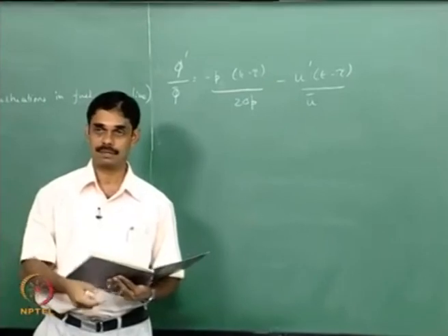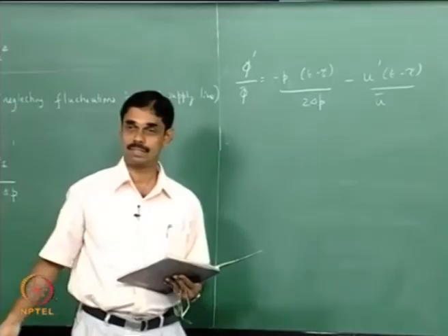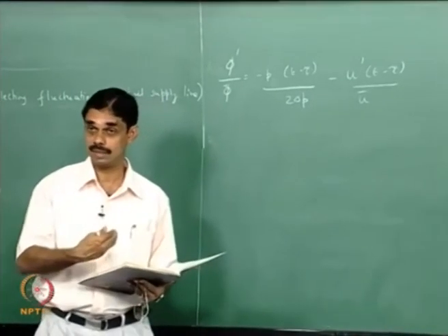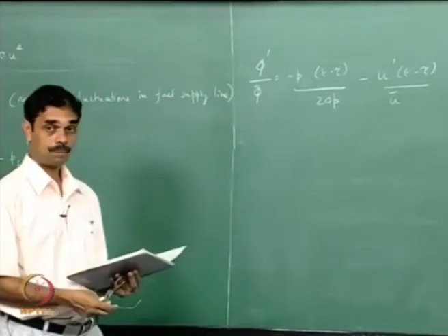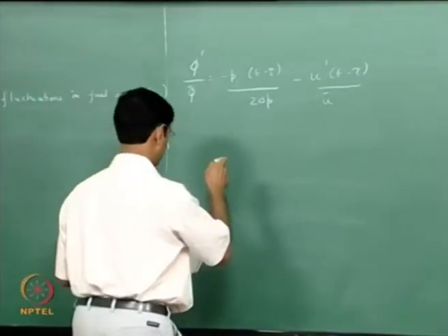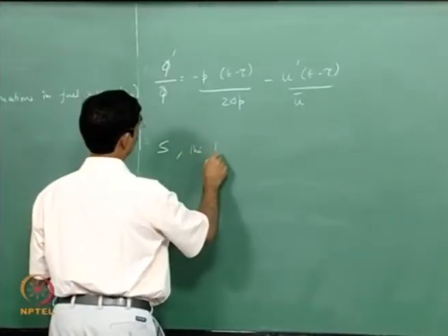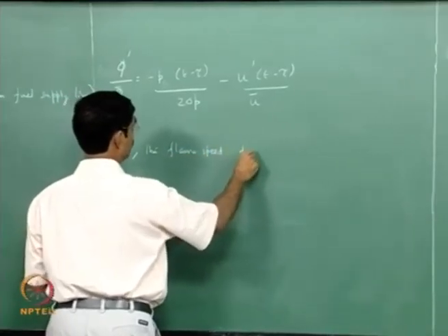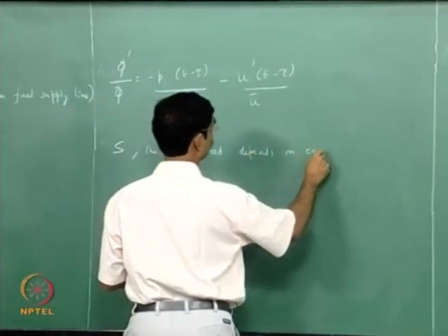Because sound has both velocity and pressure fluctuations, when the velocity is increasing, the airflow rate will increase, and when the velocity is decreasing, the airflow rate will decrease. So that also causes the oscillatory airflow rate. So together they contribute to equivalence ratio fluctuations. Okay. So yes, the flame speed depends on equivalence ratio.